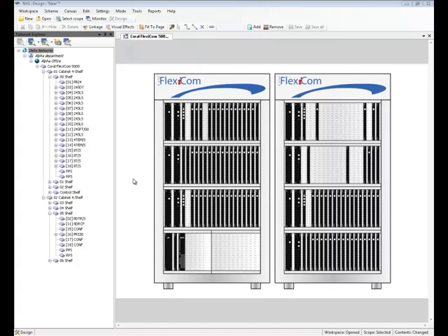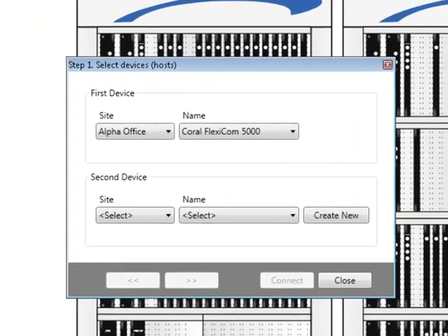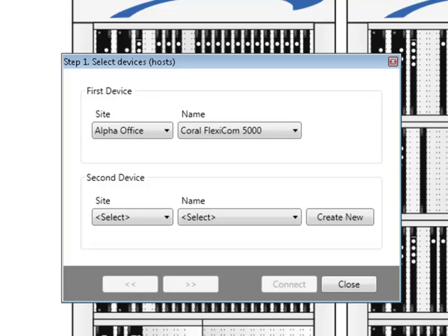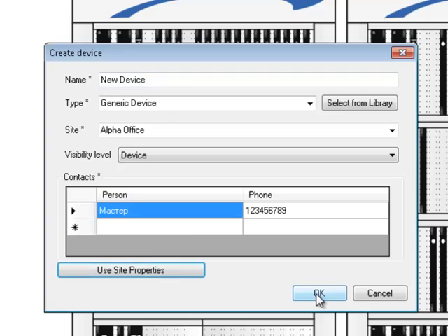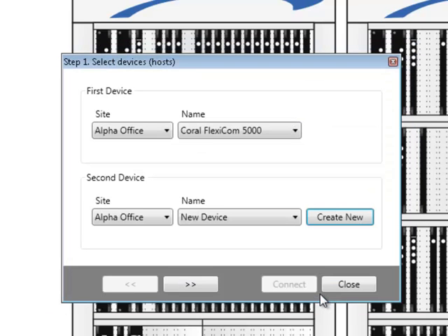One of the most important steps in corporate network model creation is configuring connection between network elements. This step can be achieved by using Connection Configuration Wizard. The first wizard step allows user to choose the device which needs to be connected to recently created PBX. If the device has not been created yet, the user can create temporary generic device, which will be connected to PBX. This device can be detailed later.